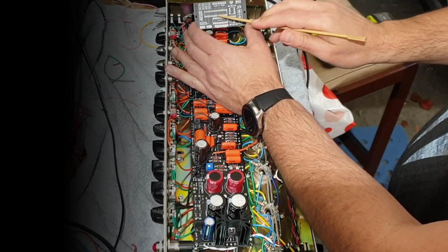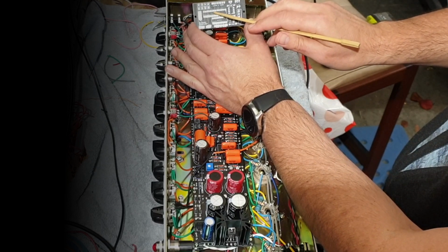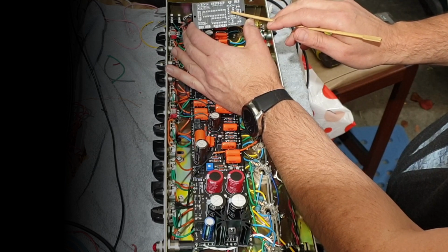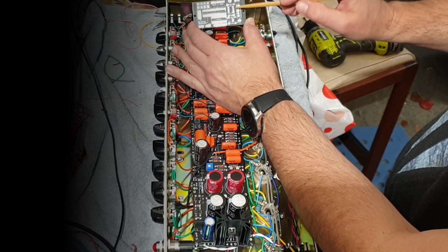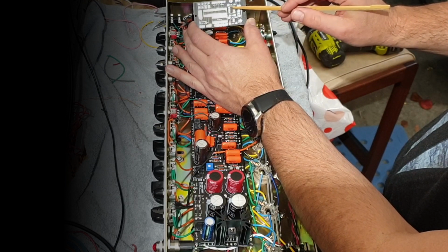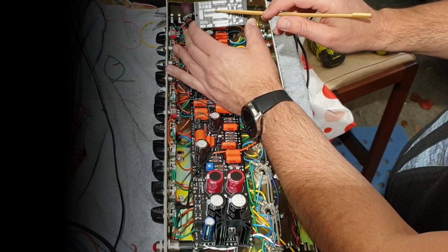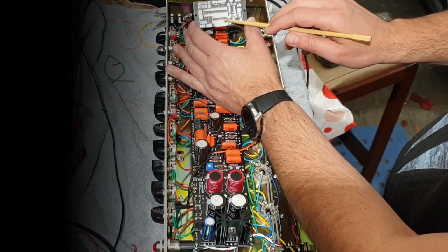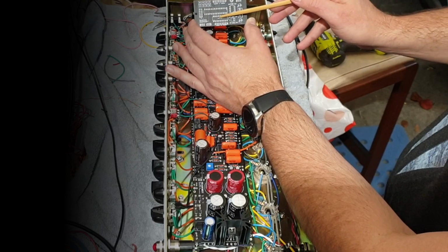This is our ATmega chip, which has got my firmware loaded on it. This chip here is the optocoupler. So this basically allows the MIDI coming in here to be optically isolated and then transmitted to the chip. And this chip down here is the NPN array, which is driving the relays.